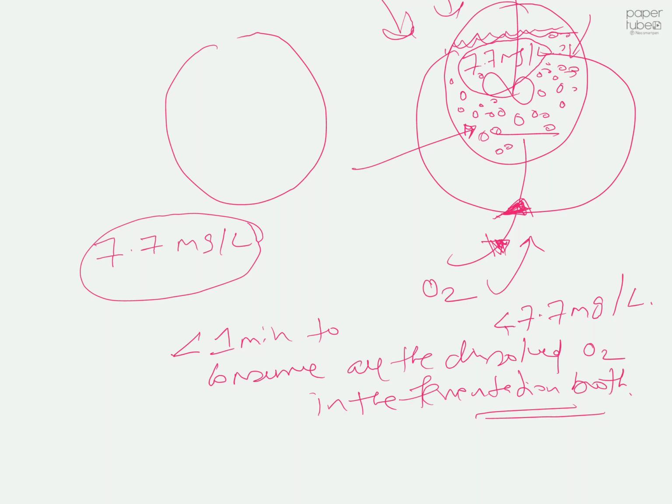So what we need to do is transfer oxygen so fast into the reactor that even if the cells are growing at a much faster rate, and the cell concentration is high enough to consume all the oxygen dissolved in the solution, you have to replenish the water with new oxygen. So you have to transfer more oxygen into the water, yeah? This is the part where mass transfer becomes really important.